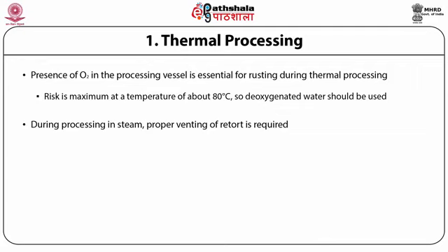The removal of air from the retort prevents pockets of air from surrounding individual cans and insulating them from the steam, the latter situation leading to underprocessing.